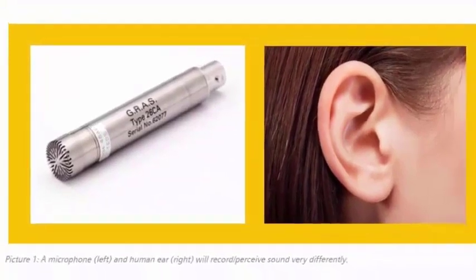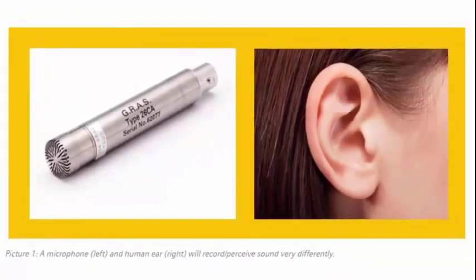There are frequencies we hear better than others. And the A-weighting curve is the tool we use to take a microphone recording and adjust it so that it's representative of how a human being would perceive that noise that you measured.